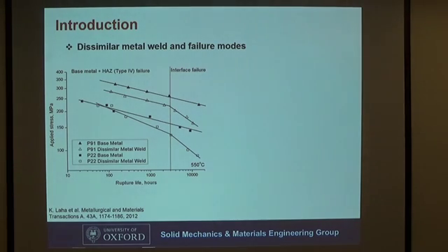So some data of P22 welded with another material has been produced by the Laha Group at the Indira Gandhi Centre for Atomic Research, or called IGCAR. And here is a collection of the P91, P22 dissimilar metal weld data with rupture life. We can find several features. First, dissimilar metal welds have a reduced life compared with pure metal at a given applied stress.